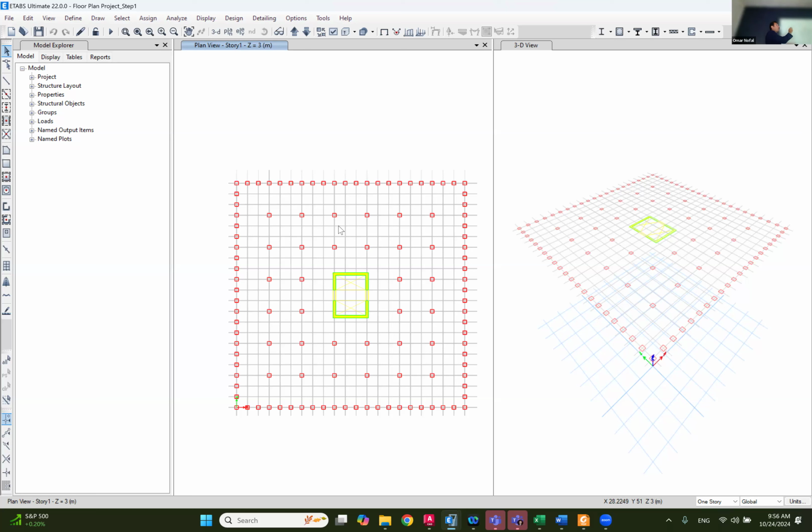What we are doing here is increasing the inertia. In this parametric study, we are increasing the depths and the thickness. All this is increasing I, which is bh cubed over 12. But E is also important. Can you imagine if this is multiplied by 2? It's always EI, so it's going to be 2EI. It's going to be much bigger.